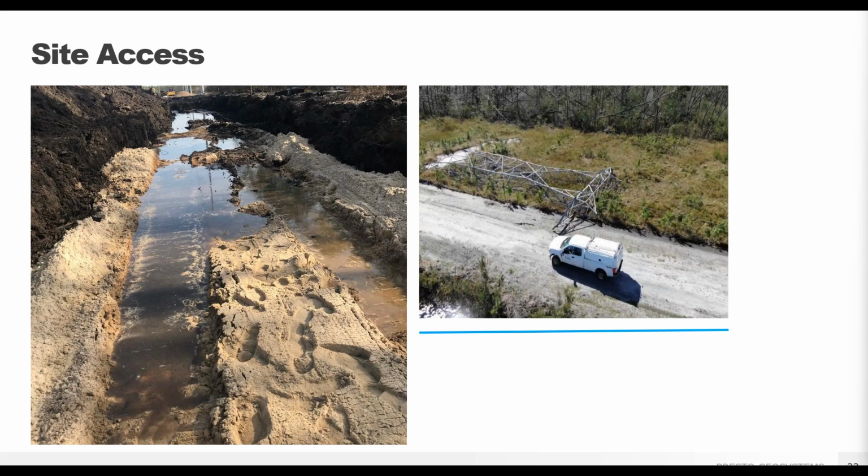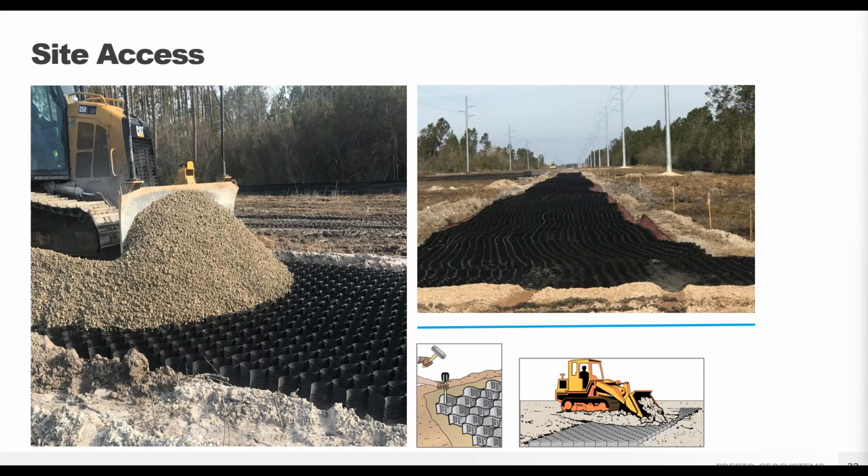An enhanced woven geotextile was placed over the subgrade, adding an additional strength layer to the system and allowing water movement without getting clogged by the sandy material. The GeoWeb system was used for access and maintenance roads, as well as pads around the towers. So, as before, the GeoWeb was expanded and held open with temporary stakes, then infilled by pushing via dozer. The GeoWeb panels were filled with a low-quality aggregate that could be easily sourced and transported to the remote locations for this project.